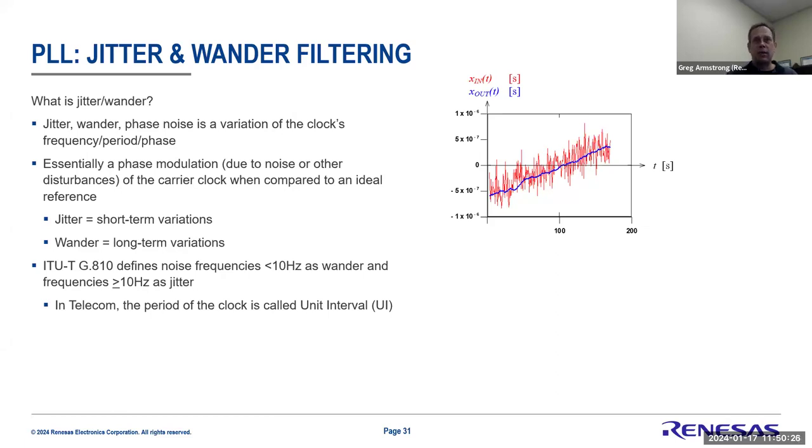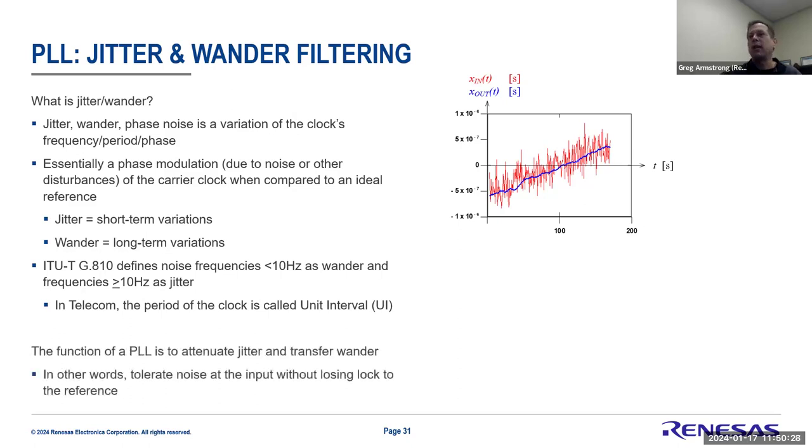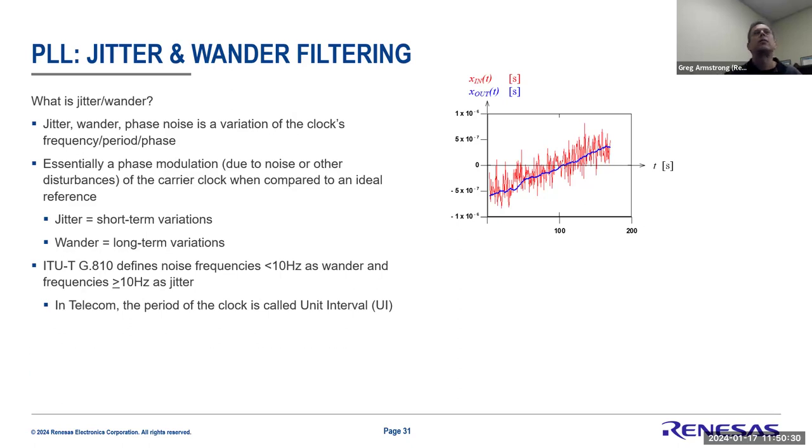When you start doing network distribution, you start accumulating noise over time. There could be rearrangements in the network that redirect timing packets, which means you have to adjust for it, things like that. And so there's all this little variation that can occur. And if you look at physical layer clocks, it's the same thing. You could have variations in your attenuation. As temperature changes, the rising and falling edges might change. And so you get a lot of what we call high frequency noise onto that clock, which is like the red line.